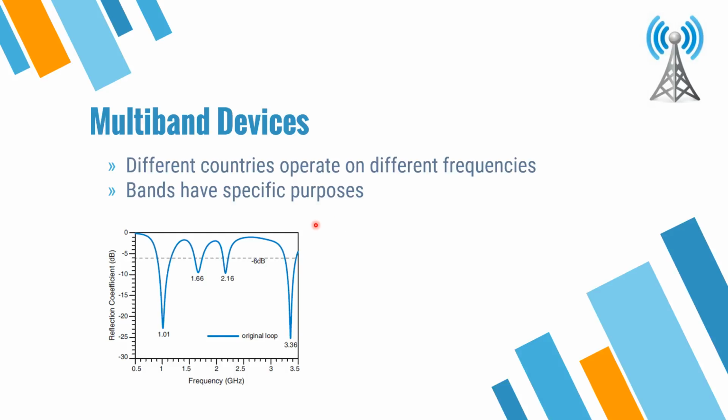So this image here just gives a graphical representation of how you would want the antenna in your smartphone to work. Ideally, what you want is your antenna to operate within bands above this dashed line here. So for example, these areas here, here, and here. And you would also want to reject anything coming from unnecessary frequency bands. When you design your antenna, you can change the physical parameters that will allow you to optimize this blue line in order to accept or reject specific frequencies, depending on the application of the device.